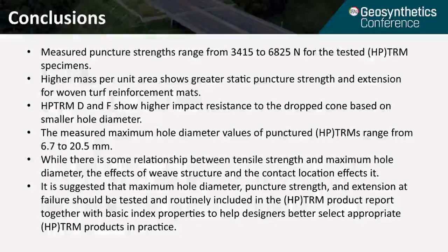It is suggested that the maximum hole diameter, puncture strength, and extension at failure should be tested and included in the TRM product reports, together with the basic index properties, to help designers better select appropriate TRM products in practice.